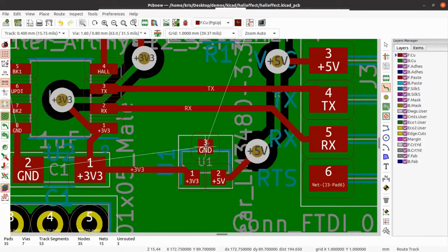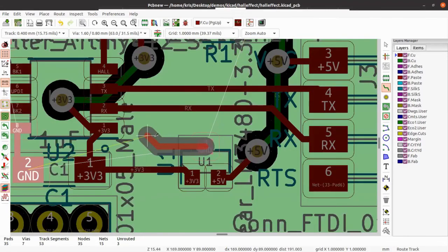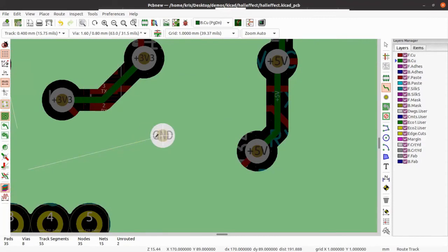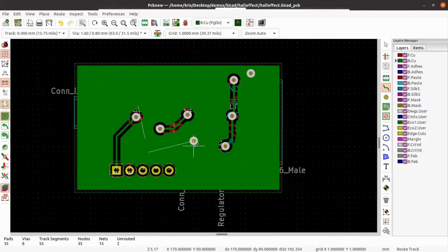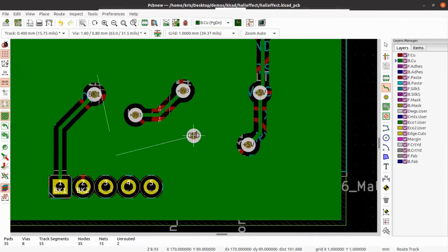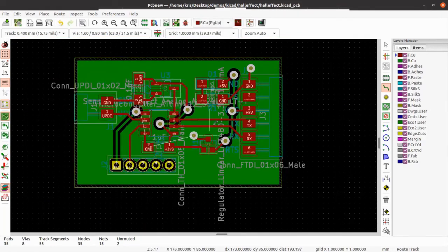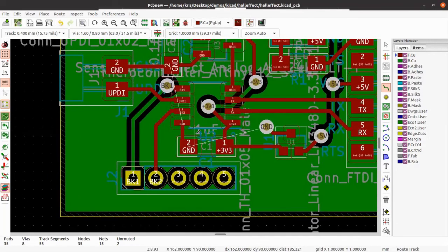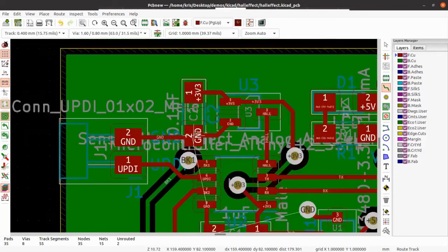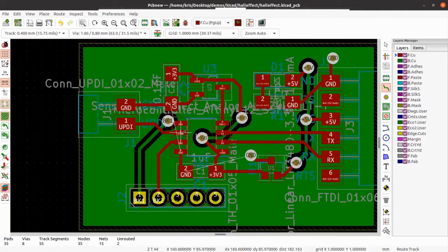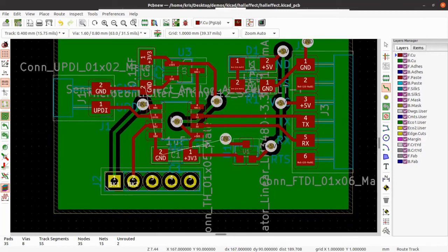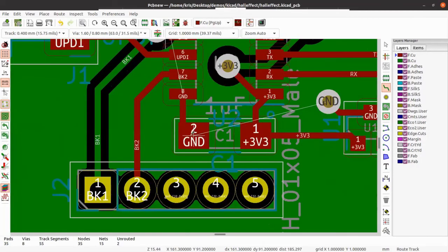The way we're going to connect them together is that I'm just going to add a via here to the ground, to the bottom layer, and hit B in order to redraw it. So now it's connected. So now there's no rat's nest. Now we also need to connect these two together somehow. So now I can also add a via from here, for example.